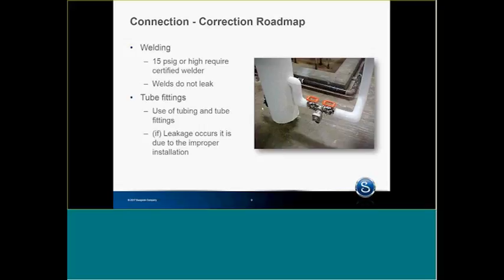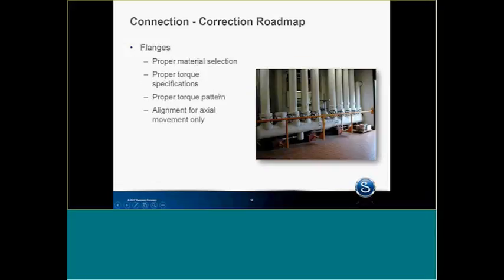And the plant says, well, can you use tubing and tube fitting at that pressure? Well, yeah, we use tube and tube fitting at 3,200 PSI. 400 PSI is not that very high of a pressure. So when you're looking at installations, as you can see in this picture, is a typical installation that we use, which is using tubing and tube fittings for installing a simple device as a steam trap station. And that's been in operation for 4 years now, no leaks. But anyway, just another way to get around using threaded connections.